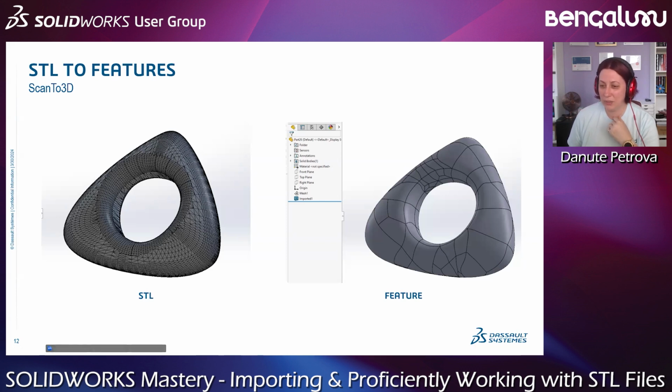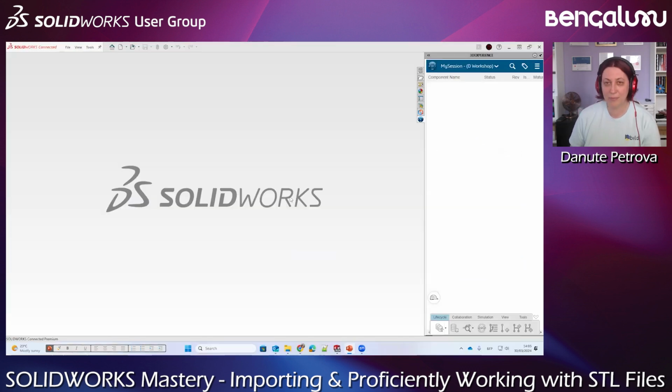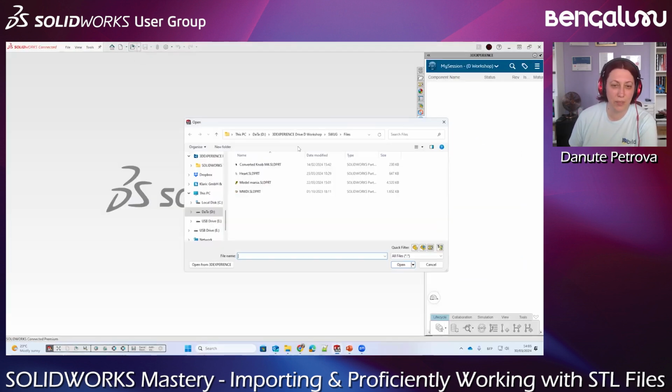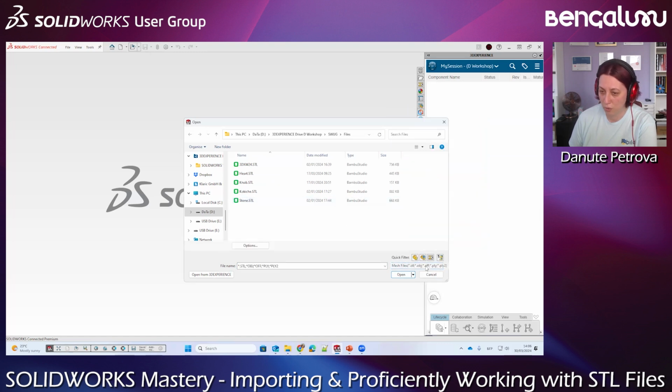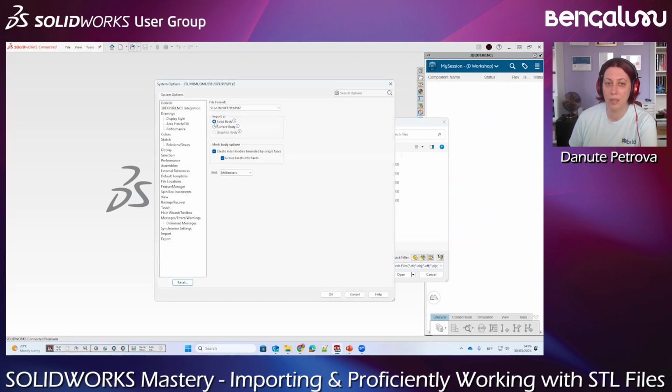Okay, so let's start SOLIDWORKS. And we will open, as I said, from this menu here. First, I will show you that if you use the standard Mesh STL object, you should go to this menu to have the options. And here you choose solid body. In my case, my default is solid body with mesh body enabled. But usually the default is like this, and that's why a lot of people say, okay, I cannot import STL. Yes, you can. You just have to come here and change your settings.